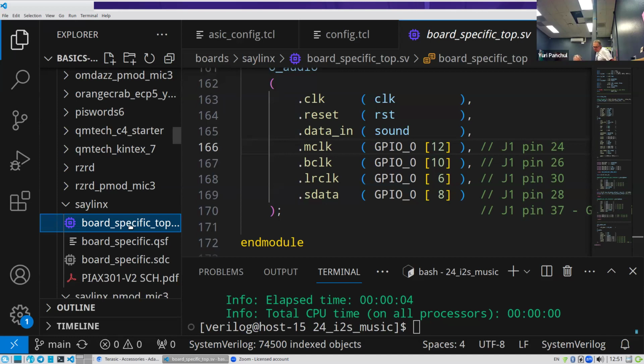So it looks like that Verilog file was just mechanically moved. The person who was putting that wrapper just mechanically put the command from another file. So let's go back to that file. I probably need to remove that command because it's incorrect.